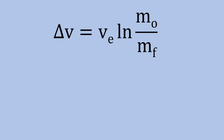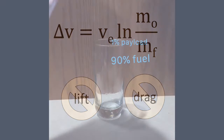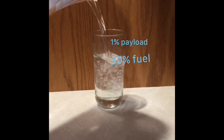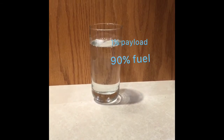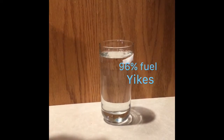One thing to note is that this equation does neglect the effects of aerodynamic lift and drag, meaning it doesn't give you a completely precise value. The equation tells us that in order to reach low Earth orbit, a rocket needs to be 90% fuel, with only 1% of its mass being the payload. Add the factors neglected from the equation, and we end up with something that's more like 96% fuel.